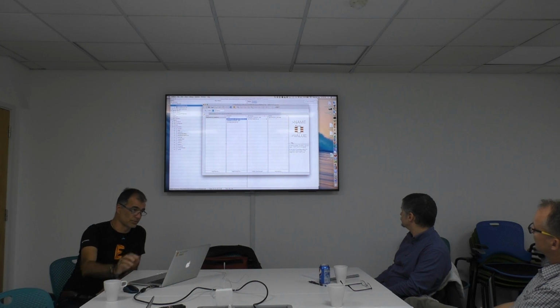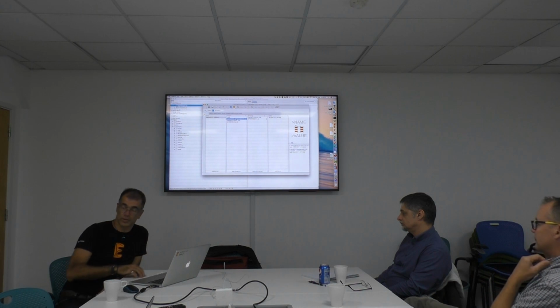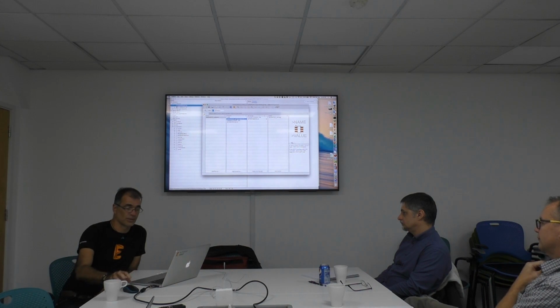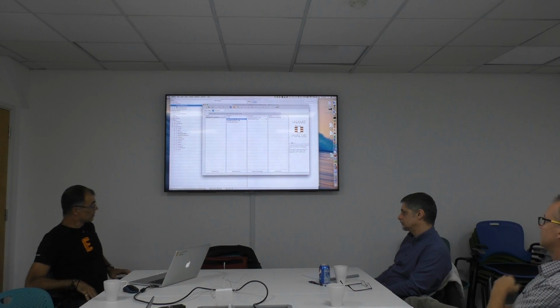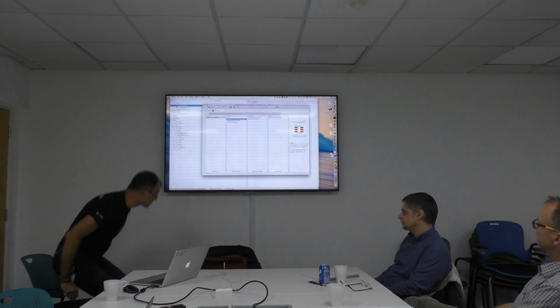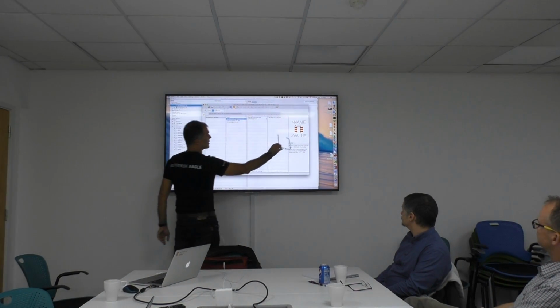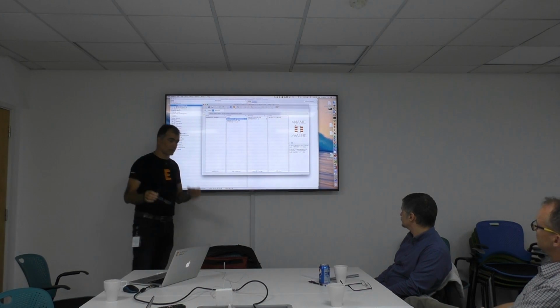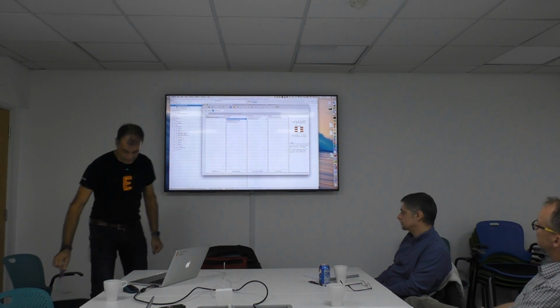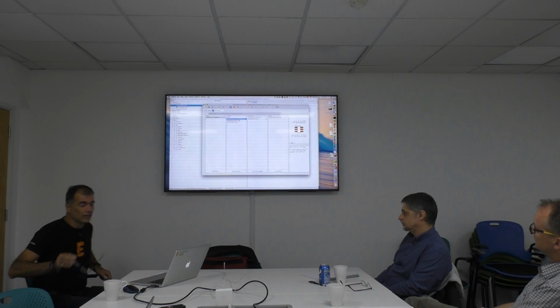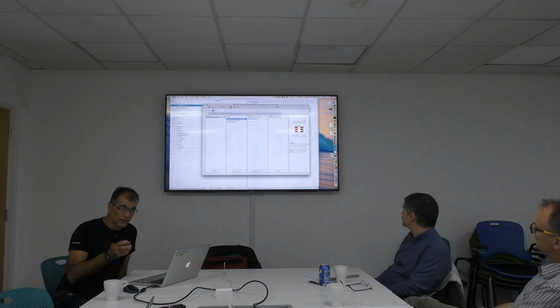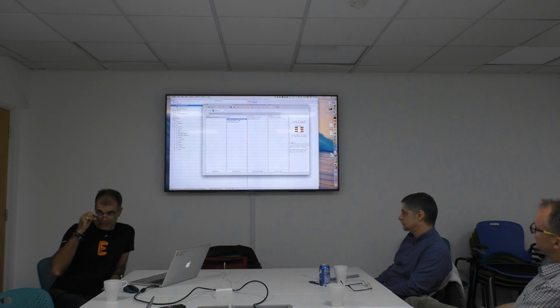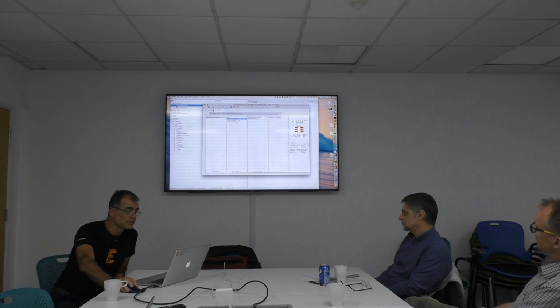I have to get used to footprints because in earlier versions we talked of packages. That's the footprint here. So that's the size of the soldering area, that's the SMD, the distances. This must be accurate, so you have to be careful. That's the one thing. And we combine symbol and footprint into a device,